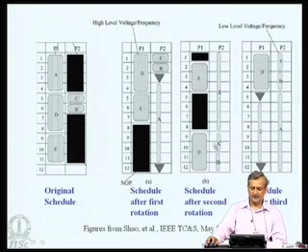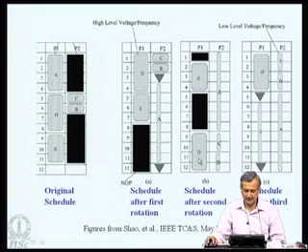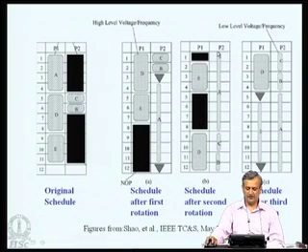Let us do loop rotation once more. Now, processor 1 does very little here, and then it executes E, and then it executes D, and in between it does nothing. And processor number 2 now runs for the entire duration of 12 cycles, executing in lean mode at a lower frequency. So, there is a substantial reduction in energy consumption.